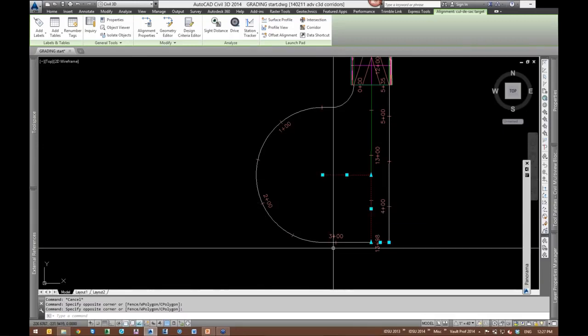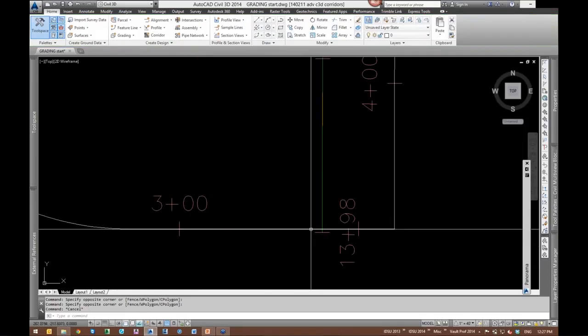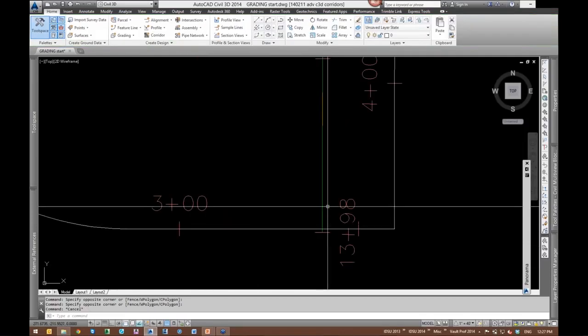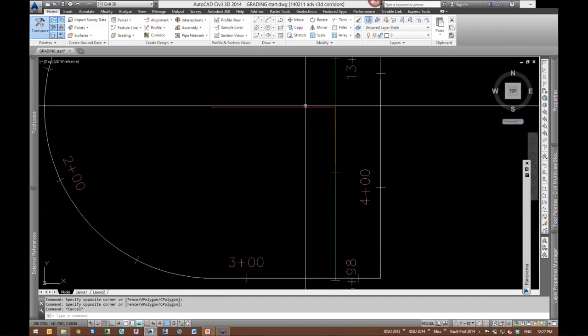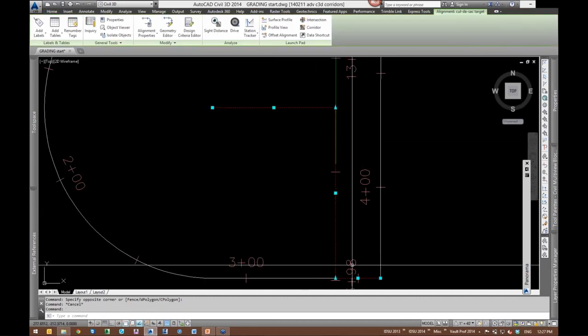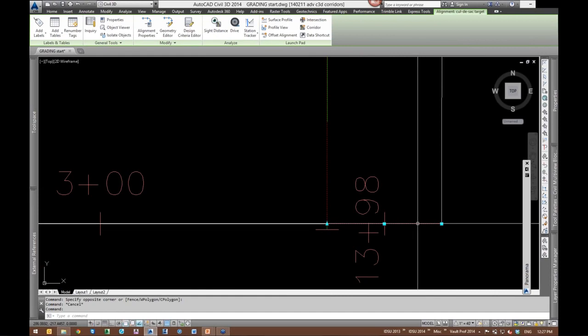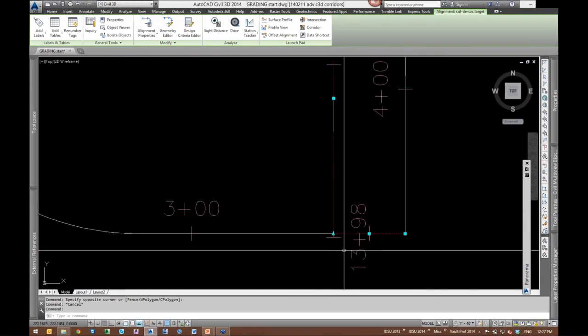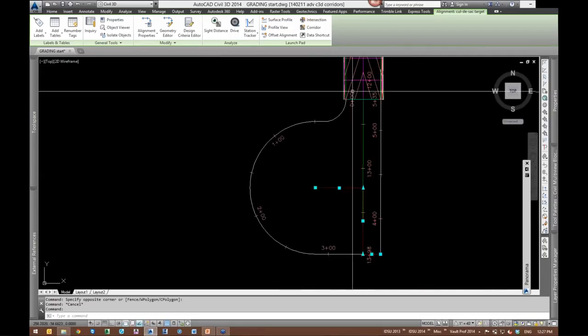And then the trick I'm using right here is we come around here with this curb return assembly. This target alignment is right on top of that baseline. So it's going to actually squeeze that lane right down to 0. And why are we doing that? We're doing that because we want to model this very simply.